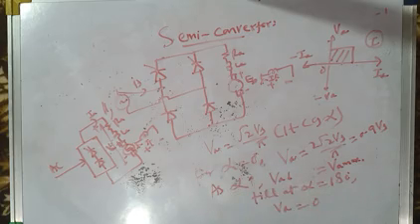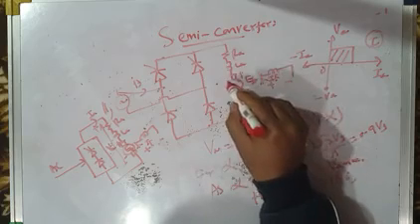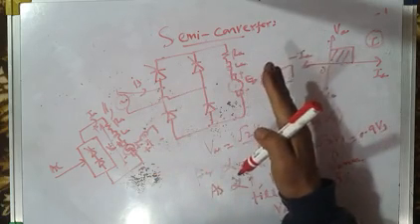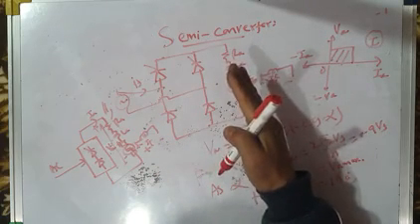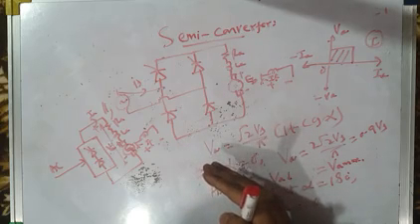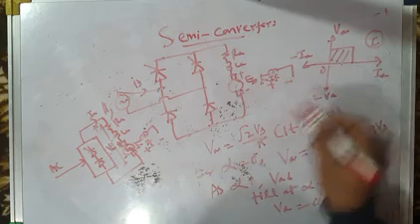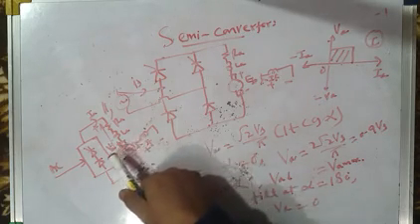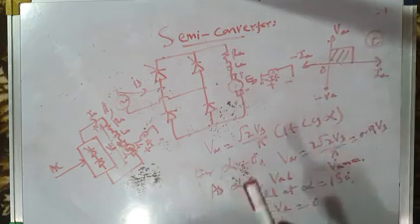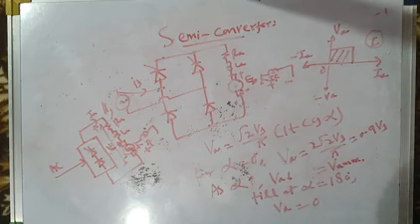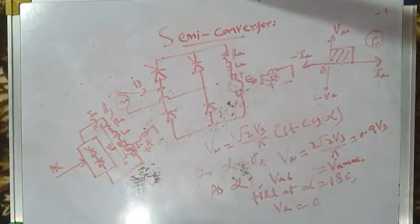It always remains positive. Okay, so therefore, if this is the DC motor, we can operate this DC machine only in the motoring mode. It's not possible to operate it in the regeneration mode. Why? Because the converter does not have capability of operating as an inverter. It always operates as a rectifier in only first quadrant. It can operate only in forward motoring mode, not in regeneration mode.